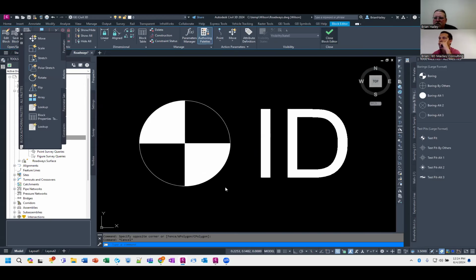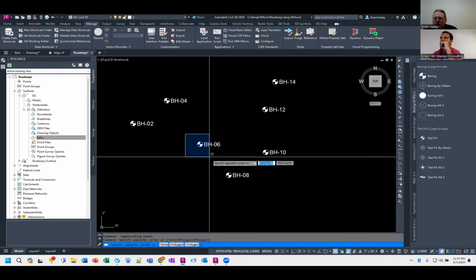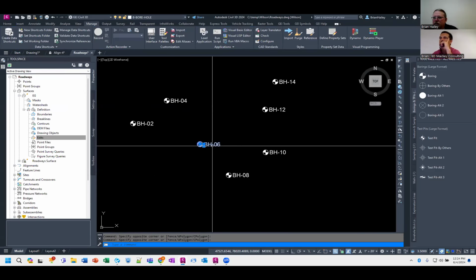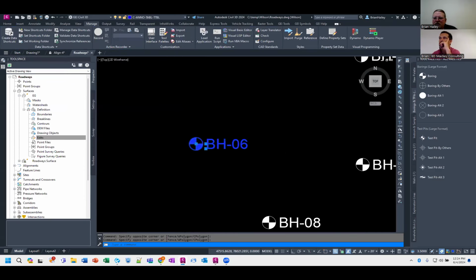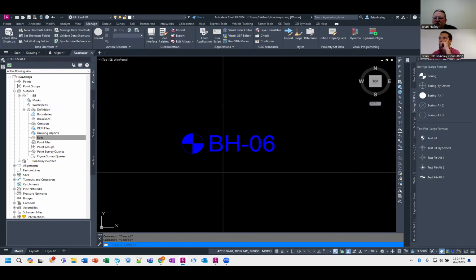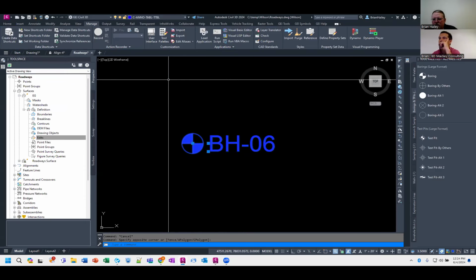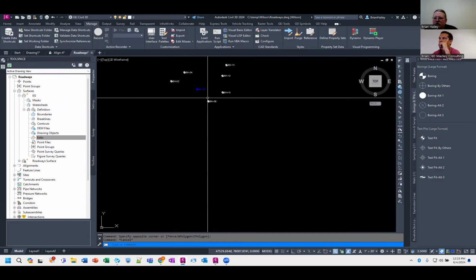Right, so if I take this block here, or rather, more technically, this block reference, and I put it on this layer here, you can see it inherits the properties of the layer that the block reference is inserted on. So that's what layer 0 does. Same thing applies to styles.